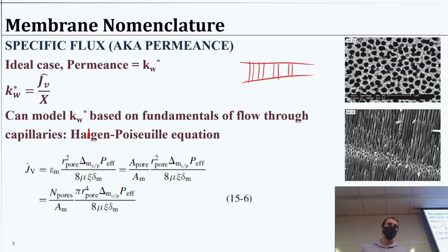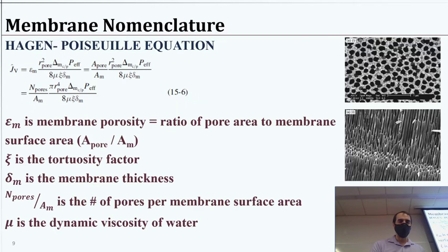This also means that if we are getting some sort of fouling and we're noticing that it's affecting our permeance, or our flux and pressure requirements, then maybe we can better understand the fouling process itself, given that our baseline assumption when it was close to ideal was flow through capillaries. So how did the fouling change that? Maybe we can use that to better understand what's happening here.